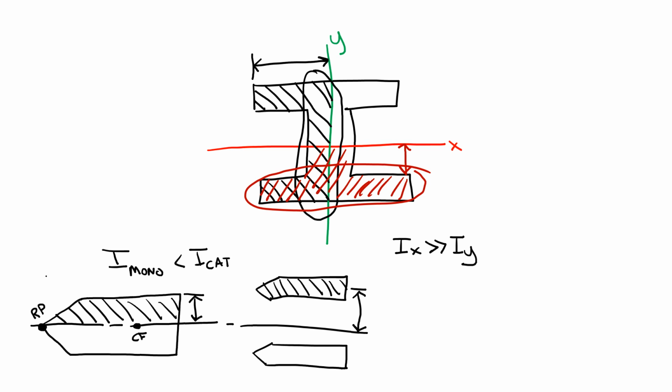It's the other axis that really matters, because if you put your axis here, then all of this area has to rotate around this axis, and you'll get a specific value for your moment of inertia. However, if you place your moment of inertia axis here, you'll get a different value, because you're only looking at an area on one side of the axis.